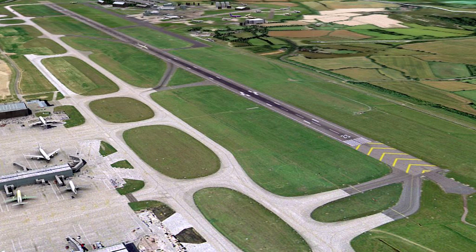Even if a pilot is taking off from the other direction, he cannot use the stopway as an extra length at the end of the takeoff run. Even when landing, the pilot must not use the stopway, either to land onto or to use to come to a stop.